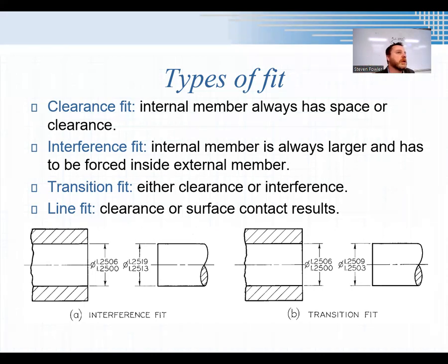And then what you're doing is you're just gambling that whatever process is used to manufacture it works exactly, perfectly. Again, you're assuming you're going to get a bunch of zeros out there. You won't, right? You won't. If I'm designing something to fit inside something else, I want to think about, how do I want them to fit? Do I want them to fit freely? Then design for a clearance fit. So whatever's fitting inside, make it a little bit smaller than what it's going into, right?